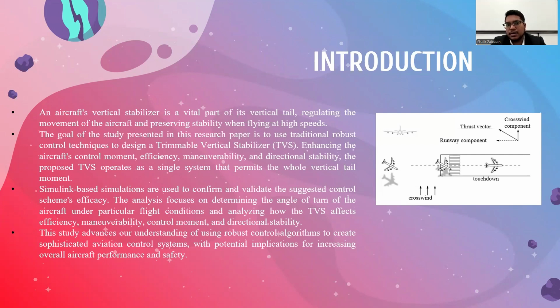due to high wind or high gust traveling from the side, the crosswind, the aircraft is not able to land, and the pilot finds it difficult during these stages. It is harder for the pilot to land, and the aircraft will not be landed on the runway. So, what happens in these cases? The pilot takes a go-around, comes back, and retries the landing.